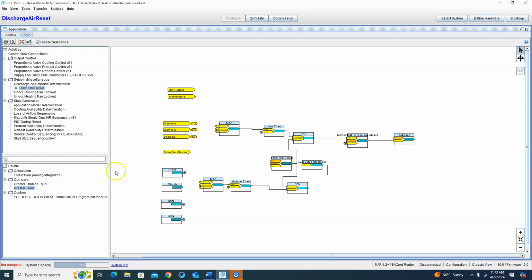So now we've got to fire the time delay. So I'm going to do an OR block here. I'm going to take it out of this, and or this less than here. I'm going to take it out of this greater than here. And that's what's going to fire this on delay. We're going to reset ourselves.